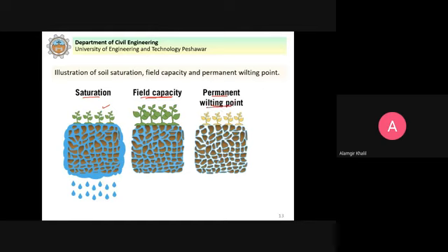So it means that during irrigation, we will now come to how to irrigate the crops, how we know to supply the water to the crops. We will not allow the soil moisture to drop to the wilting point. So the moment the soil moisture drops from the field capacity to the level where still the plants can take the water, that is the optimum moisture content.